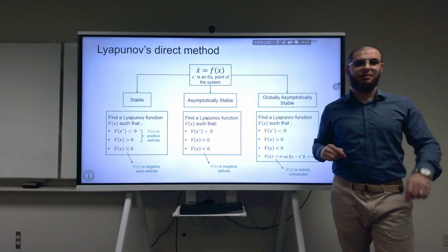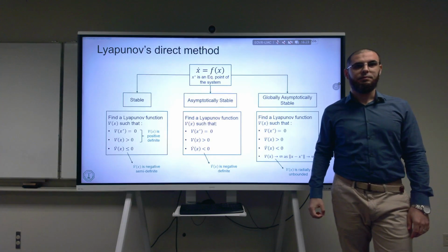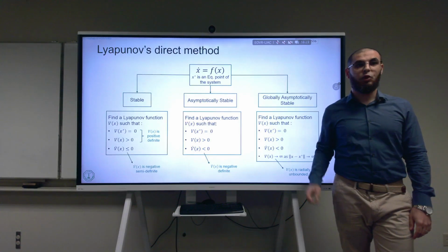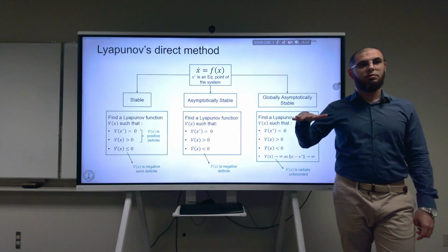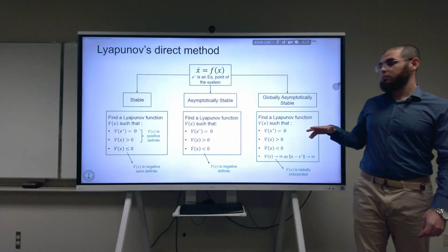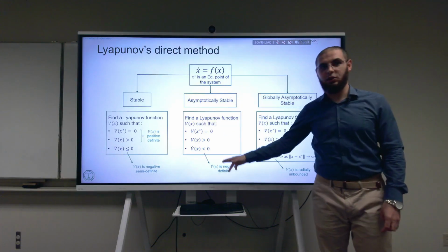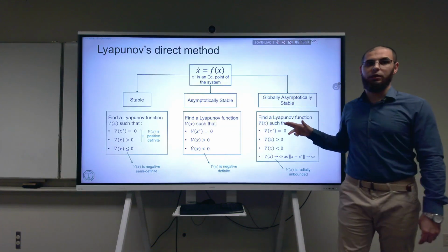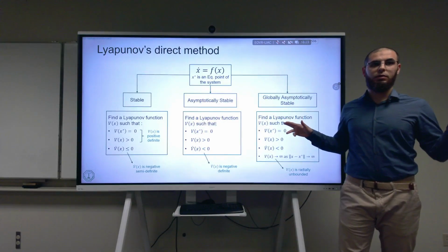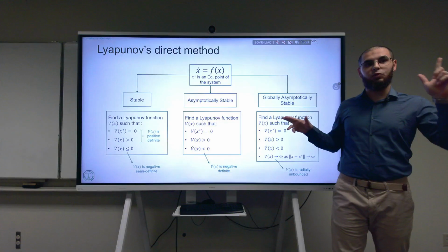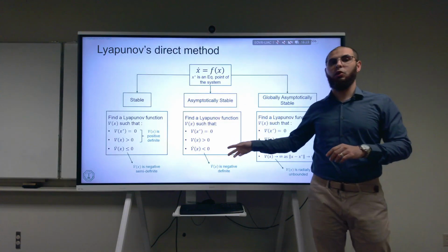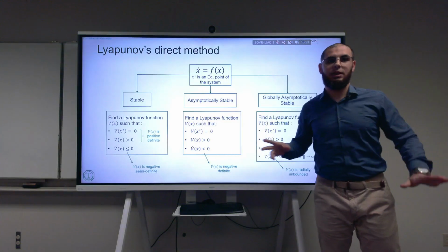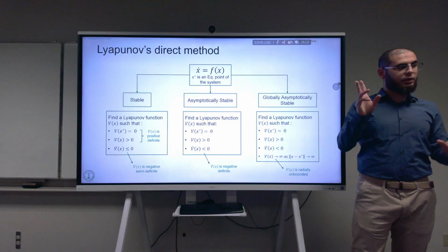If I have the eigenvalues, why do I even need to go to the Lyapunov direct method? Because the indirect method only states local stability, but the direct method can show me asymptotic stability, and global. The other one does not give global. It just says it's either unstable or locally asymptotically stable. Even stability it cannot say.